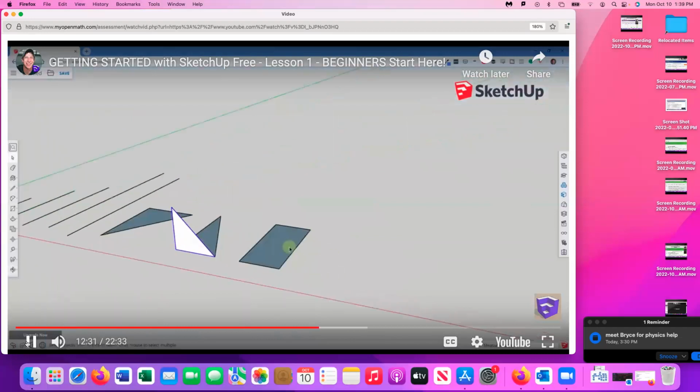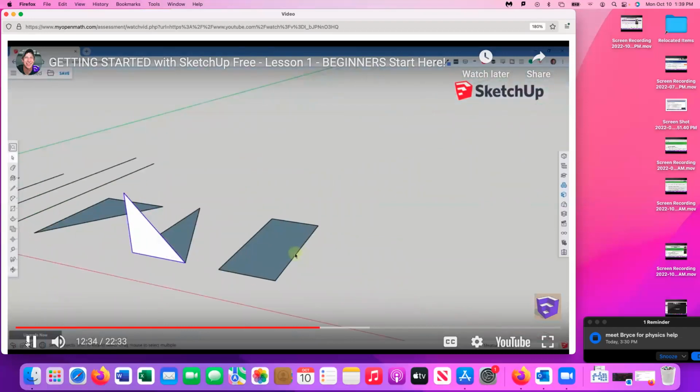And so now let's talk a little bit about healing faces and deleting edges and things like that. Because what you could do in this situation is, if you wanted to, you can select both the face or any of these edges just by clicking on them. Well, if you were to delete out this edge by selecting it and then hitting the delete key, you can see how there's no longer a face inside of the shape because it now doesn't have 3 or more closed coplanar edges. You can see how these edges are all coplanar, but it's not actually closed in.